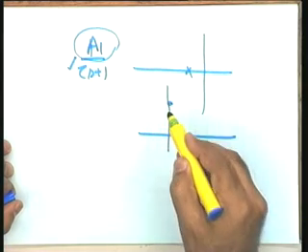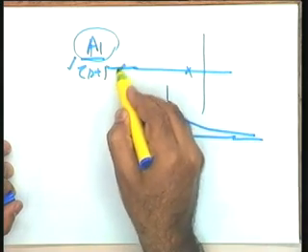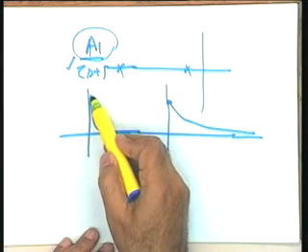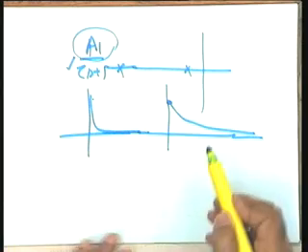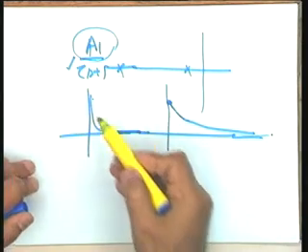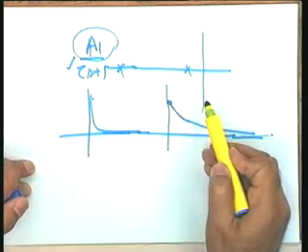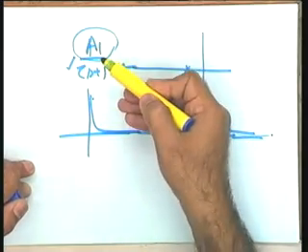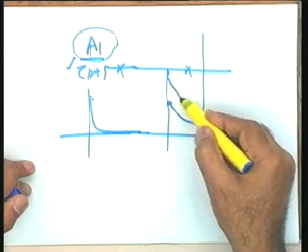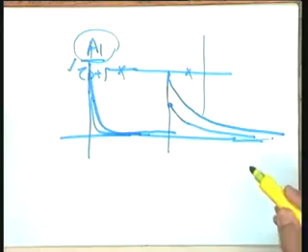An impulse response, let me take, impulse response may look like this. And if the tau is here, the impulse response may look like this. So in this particular case you find that the settling is quicker, while in this particular case the settling takes time. So it means, what I want to say is that the shape of the dynamic response is dictated by the poles of the transfer function, and the zeros of the transfer function only change the magnitude of the response. That is, your response may become like this depending upon the zeros effect. The response may become like this depending upon the zeros you may change.